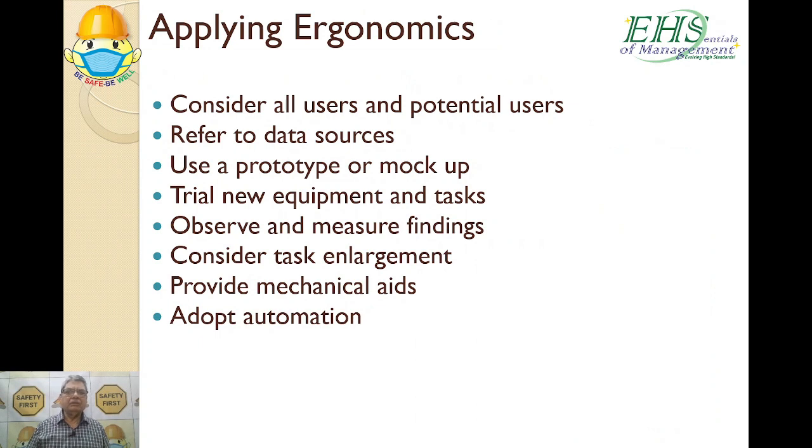So how to apply ergonomics? Consider all users and potential users. When you are designing a machine or workstation, consider all users and potential users. Refer to data sources. Whatever data there is about illness or injuries or any other problems with working on that particular workstation, refer to these data sources. Use a prototype or mock-up. First prepare a prototype, then have mock trials, try new equipment and tasks, observe and measure findings, then consider